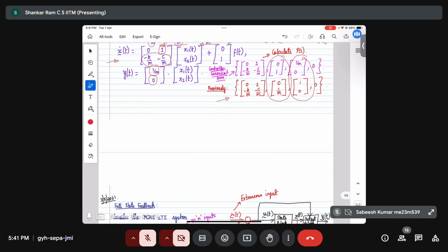No, I think Prem, let me re-articulate my statement. See, as far as physical phenomena are concerned, you may have coupled dynamics. The physics may be coupled. What do I mean by that? Let us say you may be steering a car, also braking. Let us say you write the state space representation for that phenomenon. The base state space representation may have coupled equations. But you can always apply state transformations to decouple the state space representation in some arbitrary choice of state variables. It may not even have physical meaning.